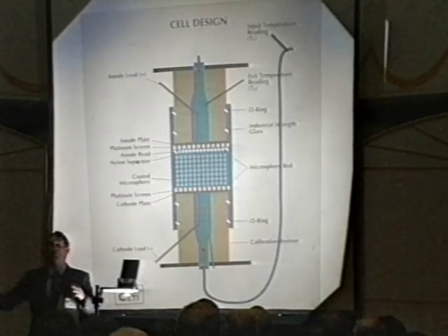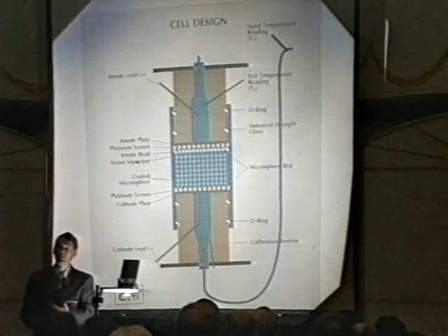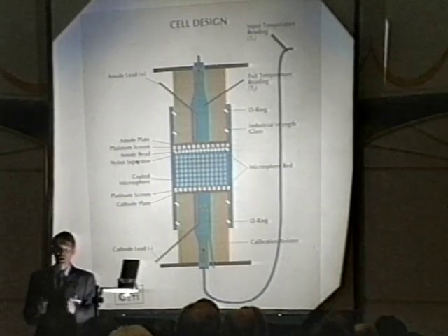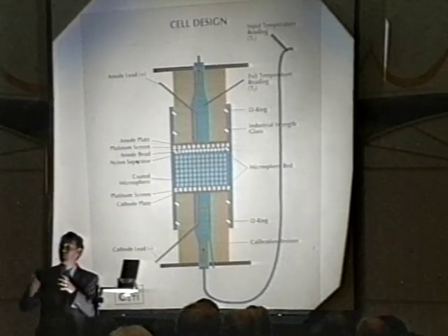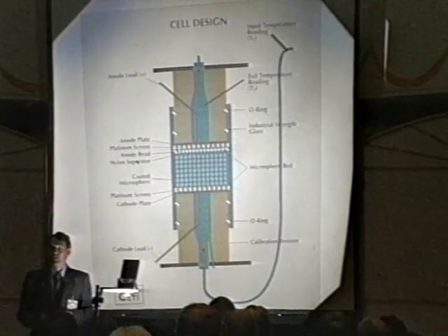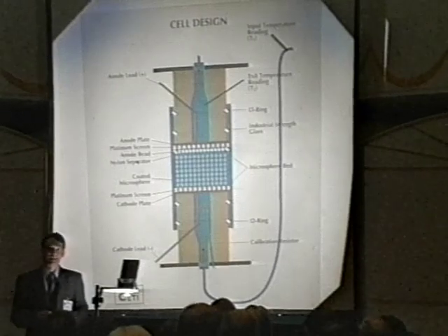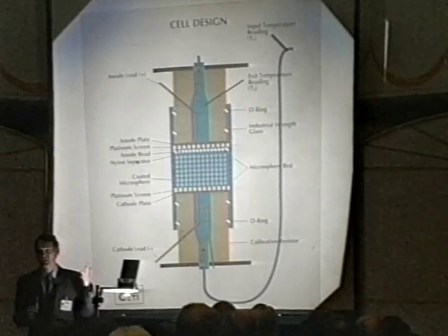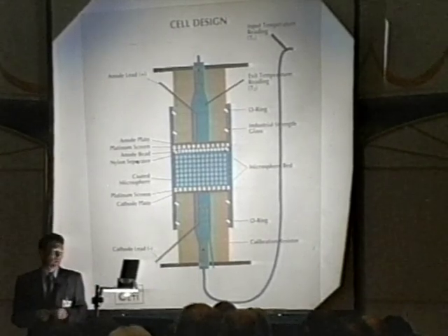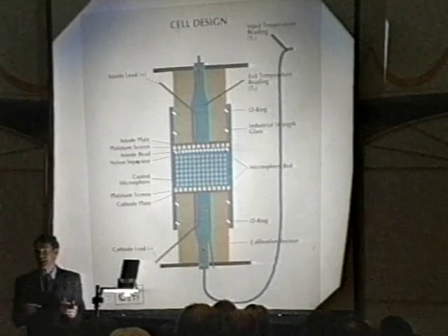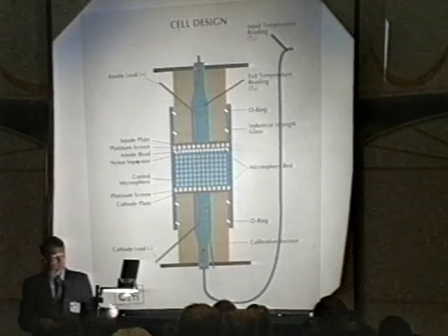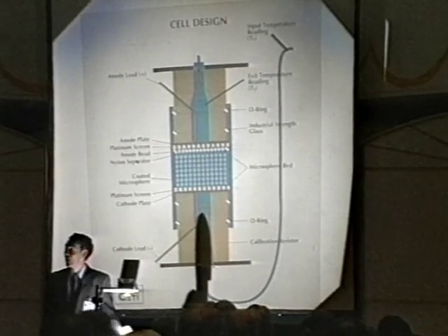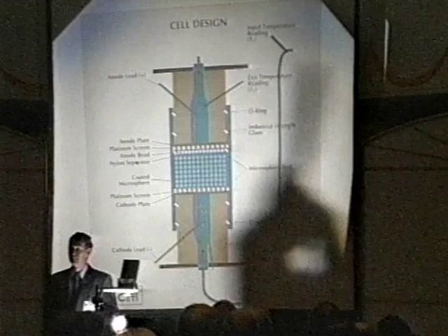We did not bring all our bench meters. We've got handheld meters, you know, things like that. So keep that in mind when you look at it. We also glued things down, packed insulation inside. The one out here is probably about 80% or so thermally efficient, 85, 86. The one that some of the runs were done were 96%. And by that I mean the resistive heating, how much is seen by the water flow.